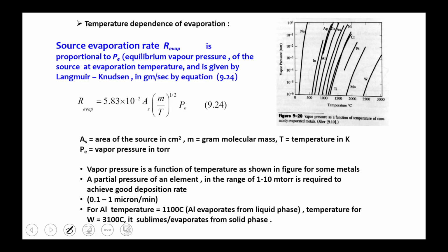Like gallium oxide, Ga2O3 will remain in the amorphous state at room temperature, but it will change into its beta phase or alpha phase or gamma. There are phase types there. It will change at around 800 to 900 degrees Celsius, meaning it will convert to semiconductor behavior at 800 degrees Celsius. So if you set your substrate temperature to 800 or 900 degrees Celsius, it will automatically convert into the beta phase.